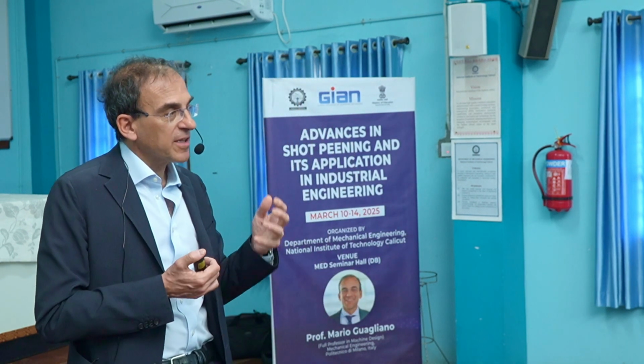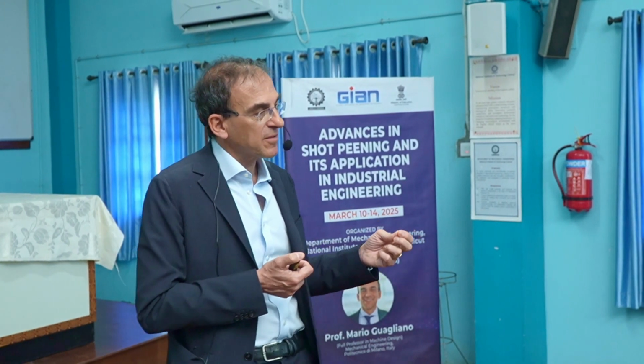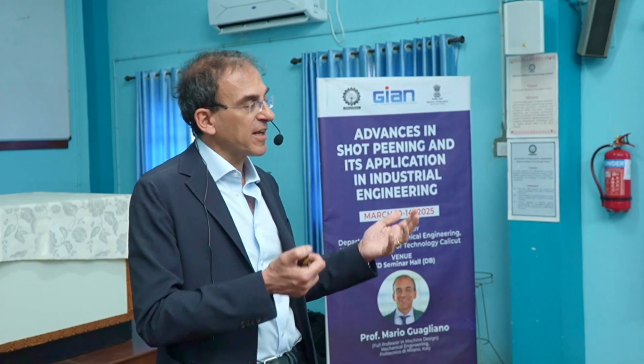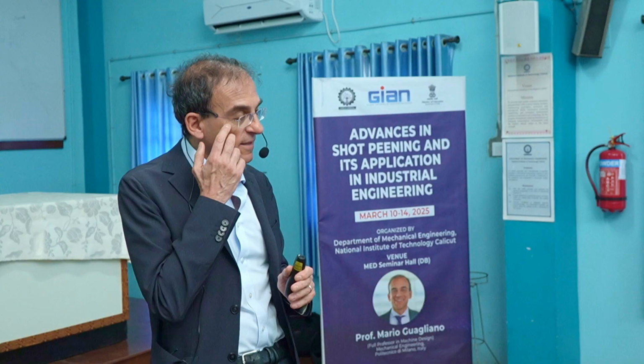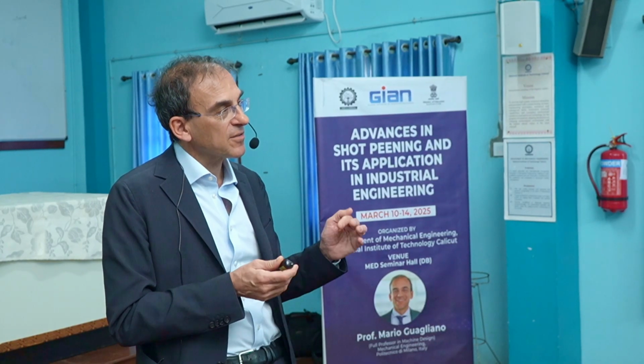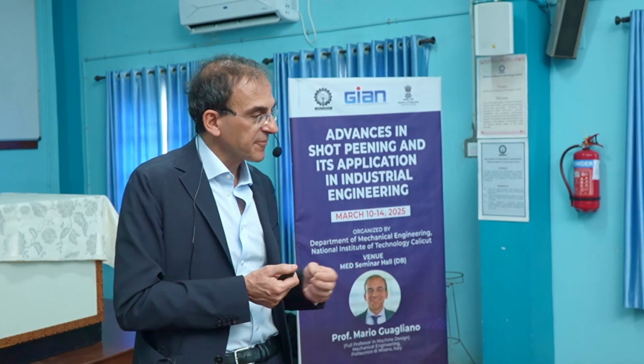Or in other words, if you are peening a material that is not very hard, or with not high strength, it's good to consider that the main effect could be not residual stresses, but surface work hardening.